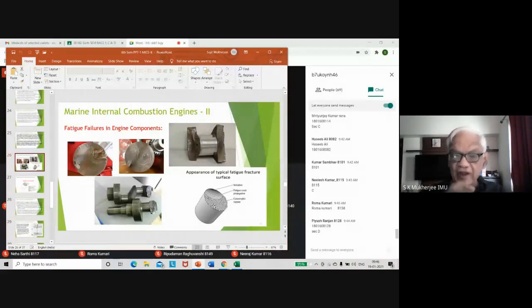That is why whenever we take out the bearing from a shaft, somebody puts a cloth over it and wraps it with a cloth and ties it with a rope. Why? Because if by mistake somebody drops a spanner or strikes it, that surface will maybe have a microscopic dent or a scratch in it. And that scratch will become the origin of failure.